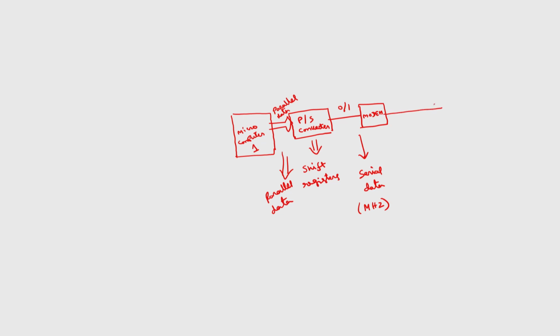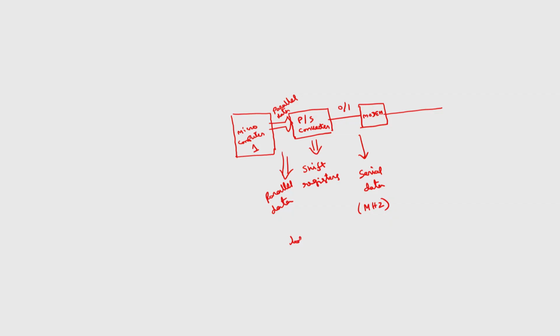The output of the modem will be audio signals. We have only two possibilities here: either we transmit logic 0, which is called space, or logic 1, which is called mark. There are different types of modulation schemes that can be employed in a modem.